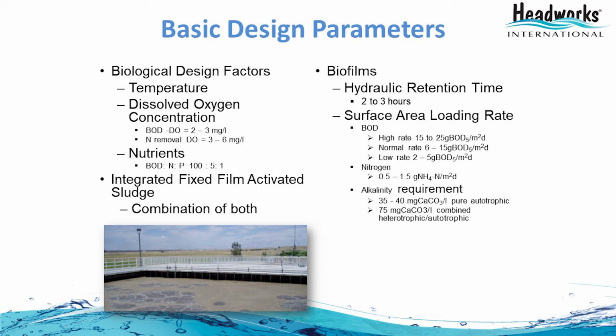Some industrial waters, like meat and poultry, will already have the nutrients. Retention time is another factor. Typically, biofilm processes have a retention time of 2 to 4 hours, including nitrification at warm temperatures. In cold temperature, it can be up to 4 to 8 hours.